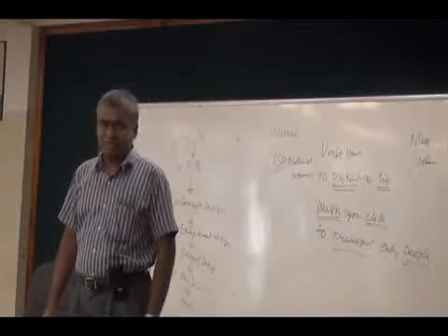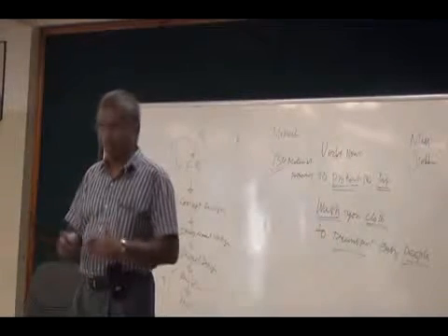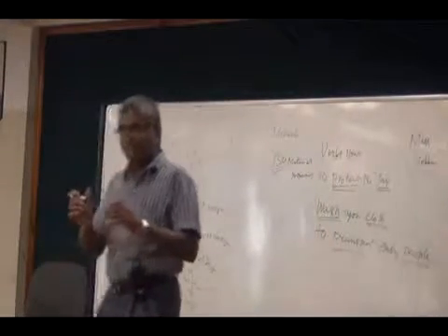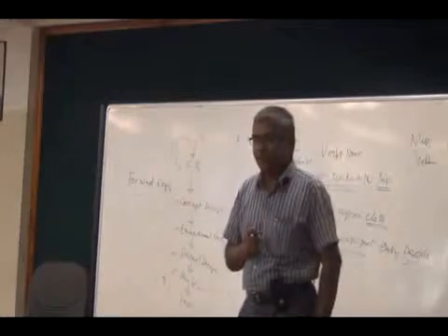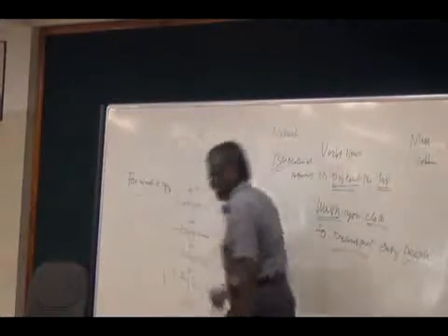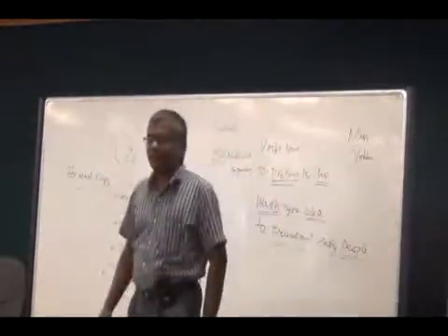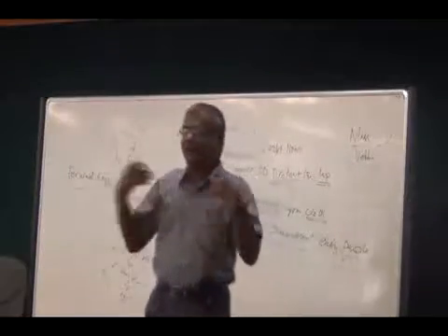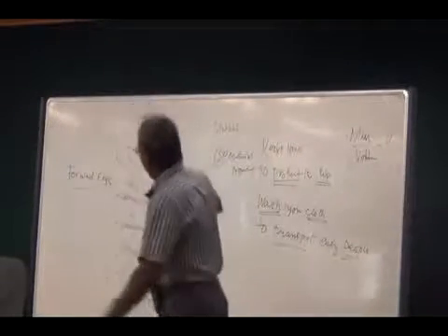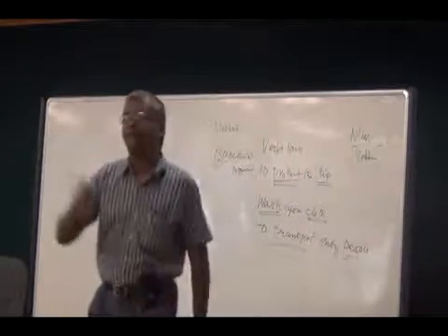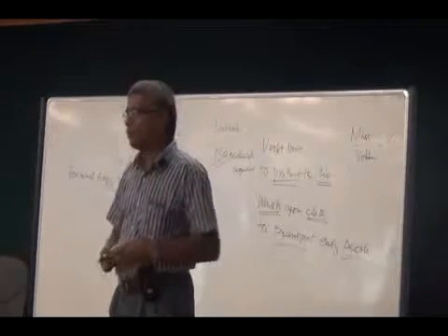You know the function, because function needs to be extracted from the part. When I say part, it is part geometry. From the part geometry and material, you can extract the function. When you extract the function, you can move back to detail design, then embodiment design, and then the concept design. Because earlier on I said design physics comes with concept. So this is one particular concept. Function, geometry and material is one concept. There could be 10 concepts. So you have identified one concept.